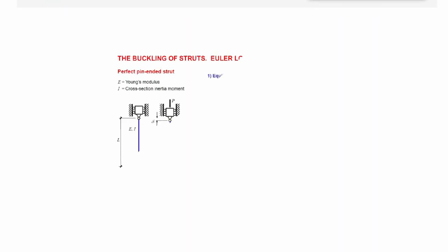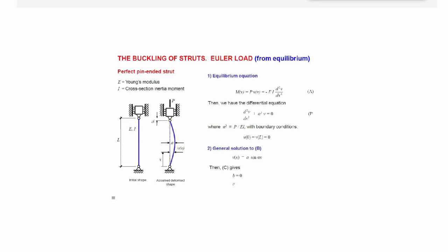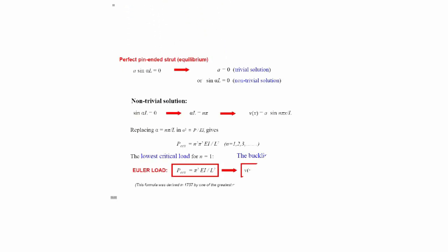Part I, Stability. Key procedure, Euler's solution for buckling of a column. Establish the equilibrium ODE equation for the beam. Use the moment and deflection relationship. Specify the correct boundary conditions. Find the general solution of the second-order ODE. Apply the boundary conditions to the general solution. The existence of a non-zero, non-trivial solution leads to an equation that buckling loads should satisfy. For each load, the corresponding non-zero solution is the buckling mode. There are an infinite number of buckling loads since a column is a continuous solid. But only the lowest one has practical engineering meaning.